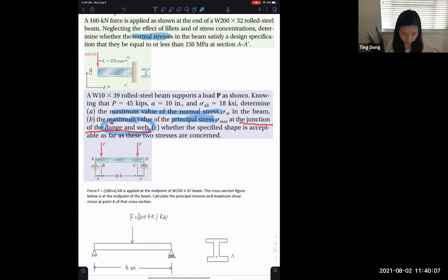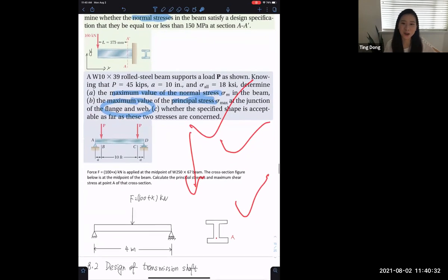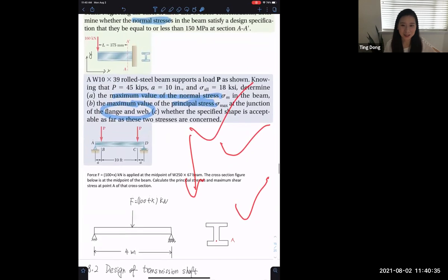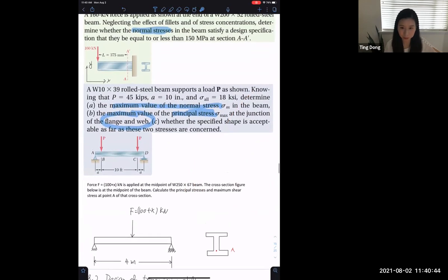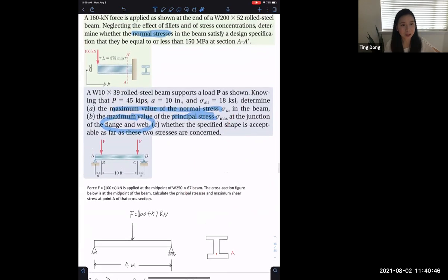The maximum value of principal stress, and of course the maximum shear stress, you just go one step ahead: R, the radius of the Mohr circle, is the maximum shear stress. So this homework problem and this quiz problem are the same problem. I just took part of this one and made it a quiz. So if you felt that quiz 6 was extremely difficult, maybe you need to check your homework and exam problems in class.